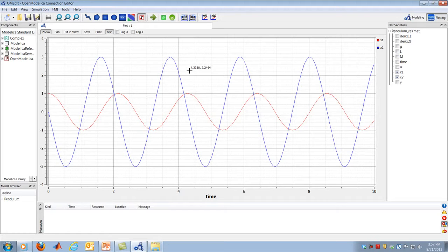When you take the derivative of that, the angular velocity will equal that quantity multiplied by the square root of g/L, and instead of cosine it becomes negative sine of time. And so the square root of g/L, the natural frequency here, happens to be somewhere close. You know, g is 9.81, length is 1, and so the square root of g/L is somewhere close to 3 radians per second, and so we would expect the velocity to peak around 3 radians per second.